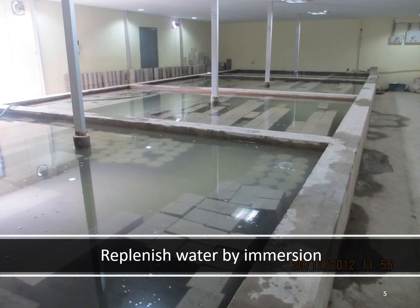And second, you need to maintain the temperature of the water inside the curing tank. The temperature of the water generally required to be maintained is 27 plus minus 2, which we have seen in our previous module also when we talked about the importance of curing in concrete elements.